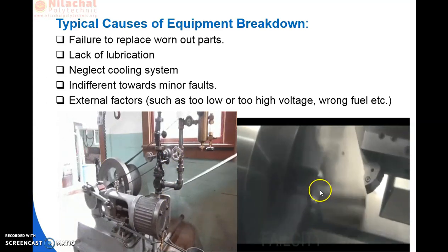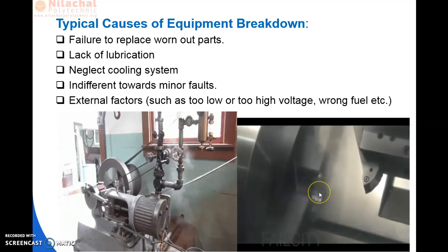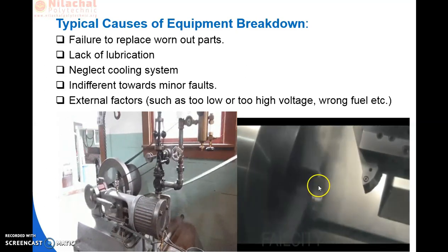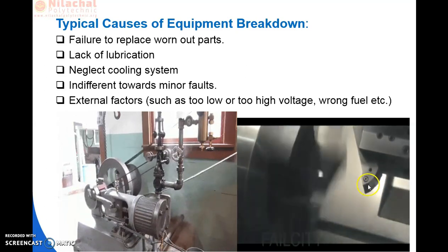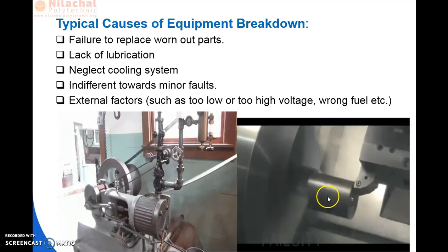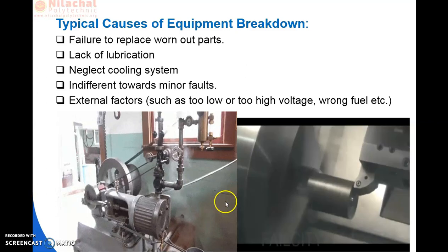Sometimes the centering is wrong. This is the second figure, where the machine part is not centered well. So while you feed the cutting tool, the cutting tool causes the job to move out of the chuck.